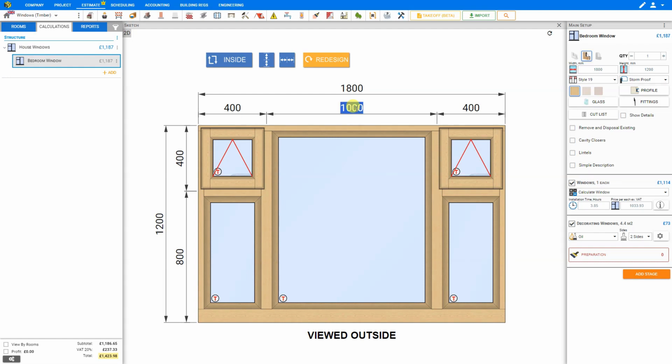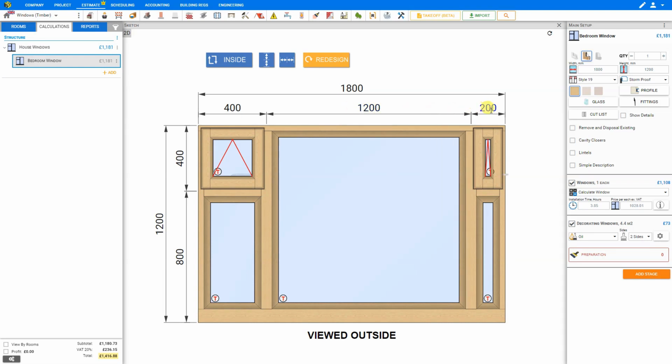And if you made an error, say we input the middle sash here as a width of 1500 millimeters, then the right-hand sash would adjust to a minimum of 200 millimeters, and it will override our middle sash value. Instead of 1500, it will adjust it to 1200 millimeters, so that all of our sashes will fit the overall window width that we specified here, 1800 millimeters total.